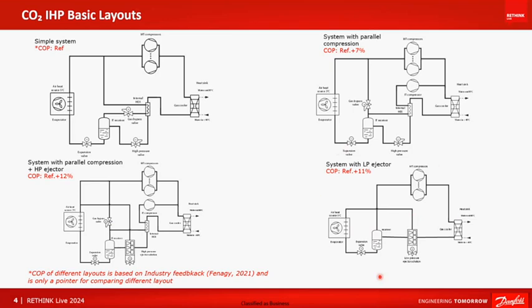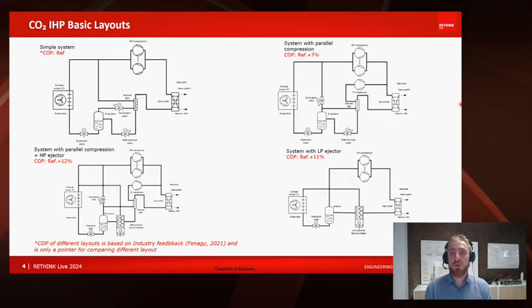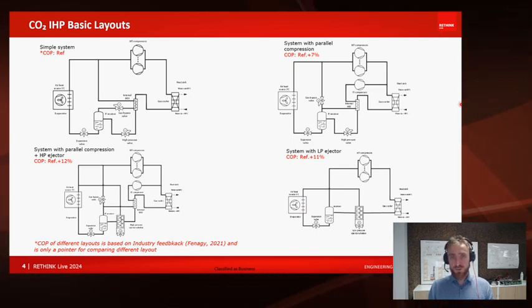This is a typical system which we would see in a water-to-water heat pump. The high pressure lift ejector can lift up to, let's say, 14 bars, and nevertheless, it can take a lower amount of flash gas from your evaporator, but it can support higher pressure differences between evaporator and receiver level. This is a typical layout seen in larger commercial or industrial-size heat pumps with air as a source. These are the four basic system architectures for CO2 heat pumps.